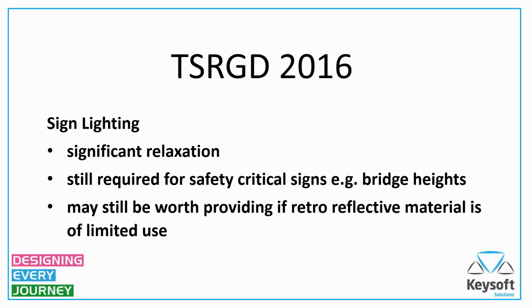And do, of course, be aware, I'm sure most of you are by now, that the best effect from the modern materials comes when you are very close to the light source. So if you're in a car, that works pretty well, but in a lorry where you're considerably higher than the headlights themselves, then it is of much limited use and in fact can have a worse effect than the old-fashioned round beaded reflective materials.